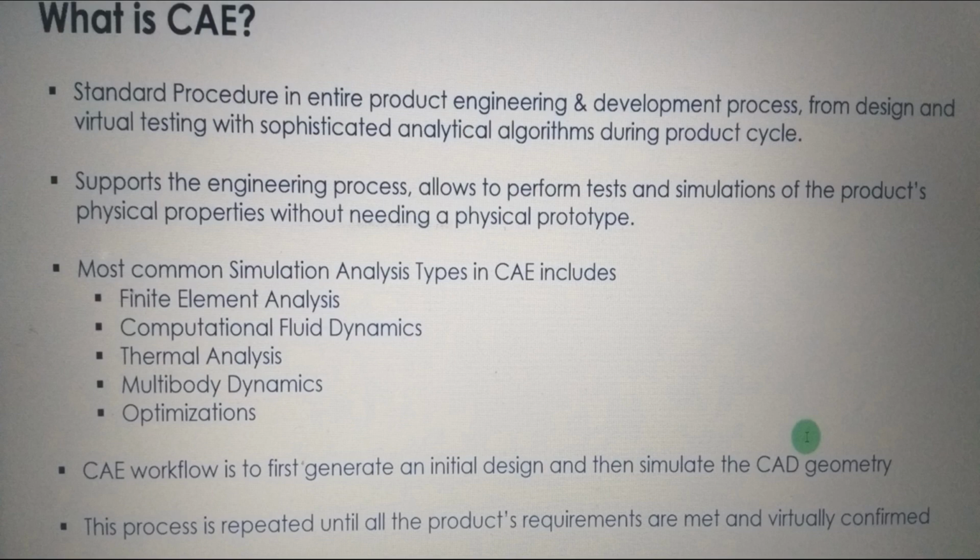And still my production engineer comes and says, no boss, this cannot be done. I cannot increase my thickness past 1 mm. What can I do then? Because with 1 mm thickness, even if I change the material, there's no change. So then I go for a design optimization. I introduce a small rib or a bead on the area where the bend is on the bracket. On the L bend, I am putting a rib, a projection or a protrusion which will stiffen the bracket.